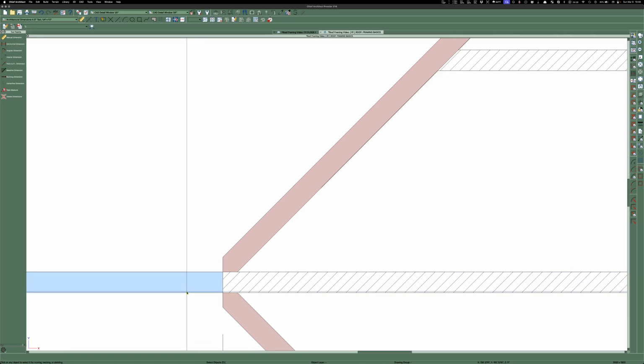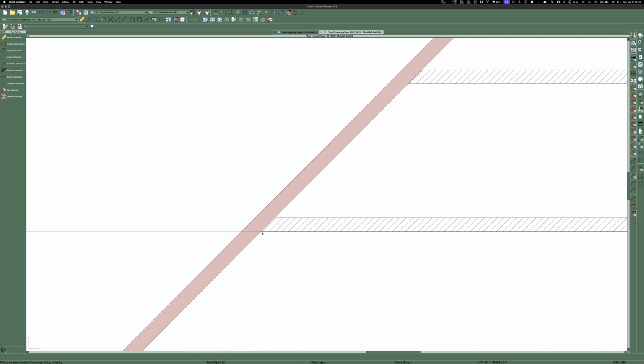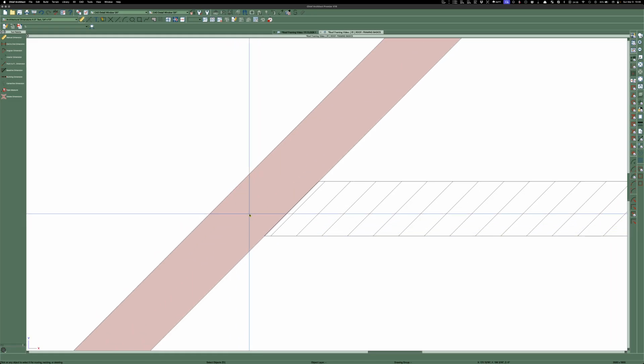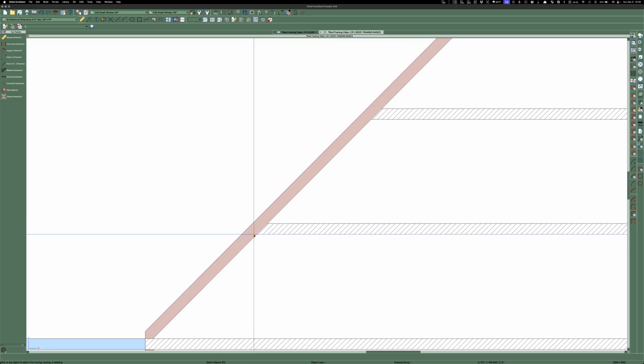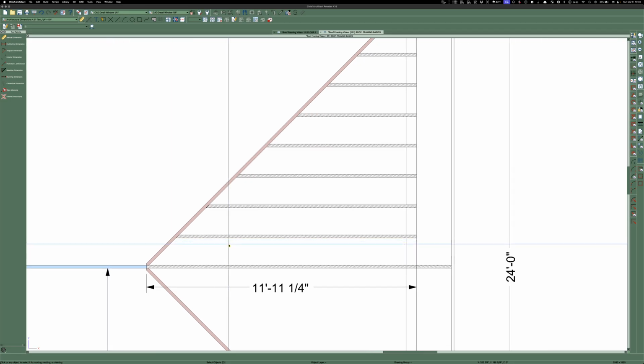That's half of the thickness when you're perpendicular to it. But when you come in at an angle, from the midpoint of this hip over to this point is more than 3/4, okay? But they go from the face and they just assume, okay, we're going to take off that same amount. And so when you see what I'm going to show you, you'll see that you can't just trust your calculator.